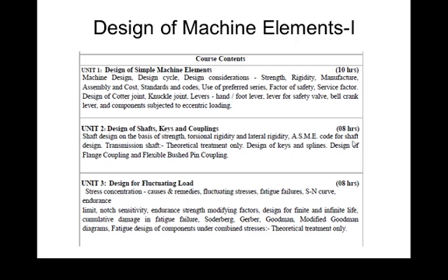It is dependent on endurance strength. Basically when a component is subject to fluctuating load, the component will fail below the yield limit. In the last year, in second semester in strength of machine elements, we studied Hooke's law and the stress strain diagram. In that there are two points we considered, the yield point and the ultimate point. For a ductile material we know that the component will be safe under load when the stress is below the yield stress.